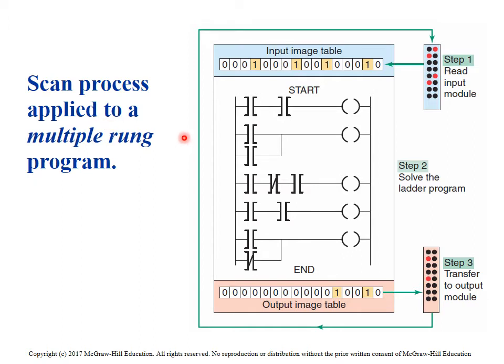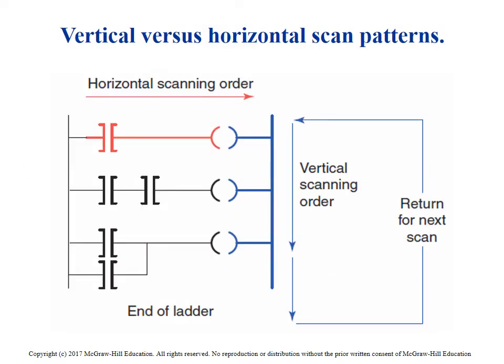And if you can imagine, you have a series of inputs, so you have multiple inputs and multiple outputs. Noting here that all the inputs are to the left and the outputs are to the right. This is the way all PLC programs work. The program scan itself, the way the program works, it always reads down and to the right. Down and to the right. So keep that in mind. When a program is being scanned, it's coming down and to the right.